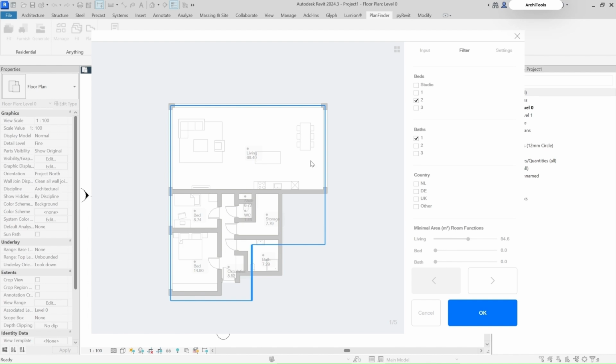The next thing which I would be talking about is you can find this blue highlighted region here, right? This is the wall orientation, the location of the wall enclosure that we had provided. But in order to create its own layout, it has somewhat tweaked the boundary of the region, and it is showing by how much the layout has been tweaked. So this is the option related to the fit. We'll also discuss how we can avoid this kind of tweaks and just place everything inside it by using the other two options, that is the furnish and generate. We'll talk about it later.